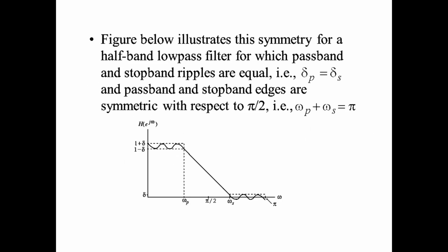So this finishes the special type of filters which come under the category of Nyquist filters. These filters will be used at various places where sample rate conversion is required and multi-rate operations are involved. The advantage of these filters is that the impulse response involves lots of zeros.